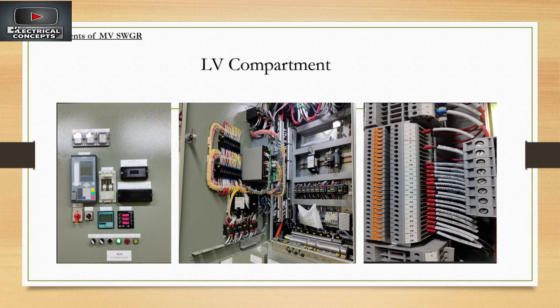For external wiring, we do the ferruling at the site. The color coding followed here for ferrules is white for internal wiring and yellow for external wiring. However, it depends on the standard and approved design.